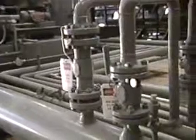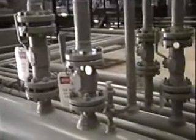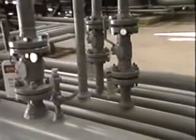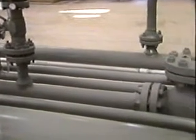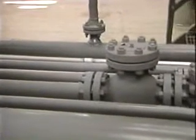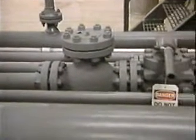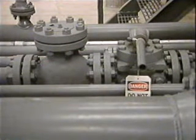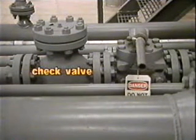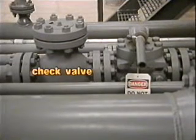The check valve prevents discharged gas from backing up into the cylinder. If there are interstage suction and discharge valves, each discharge line should be examined for a check valve. On compressors without interstage valves, look at the main discharge line for a check valve.